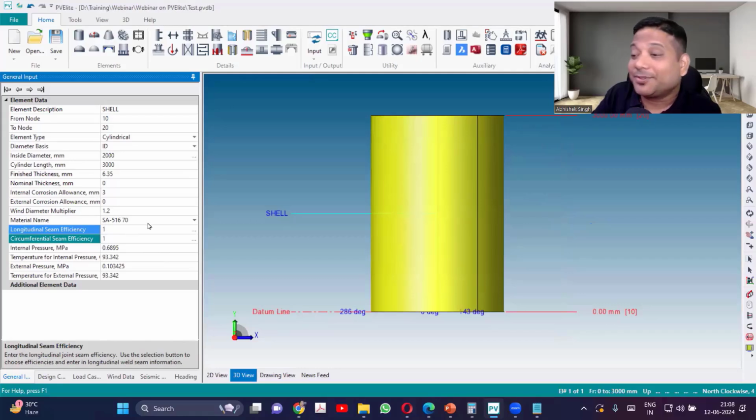If it is from pipe, you select pipe specification, SA106. Still, you won't be selecting that option, A. Even though it is made from pipe, the code is ASME. Okay, so you'll be designing with ASME, not B31.3. Make sense?